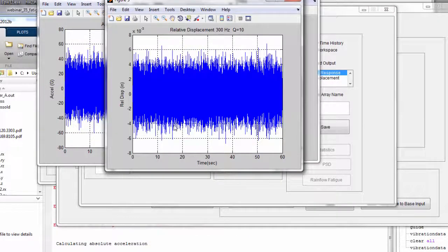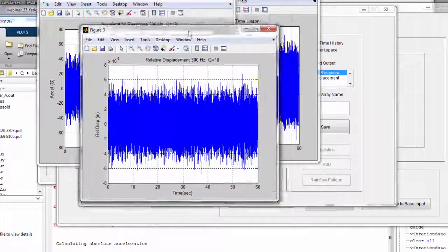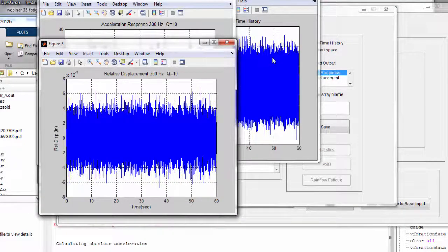So again, a couple of plots come up. Calculation goes very quickly. Oh, by the way, let's just have a little review here. This was essentially a modal transient calculation, although there's only one mode since it's a single degree of freedom system. And we use the David O. Smallwood ramp invariant digital recursive filtering relationship. And that was the same algorithm we used when we did our shock response spectrum calculation.